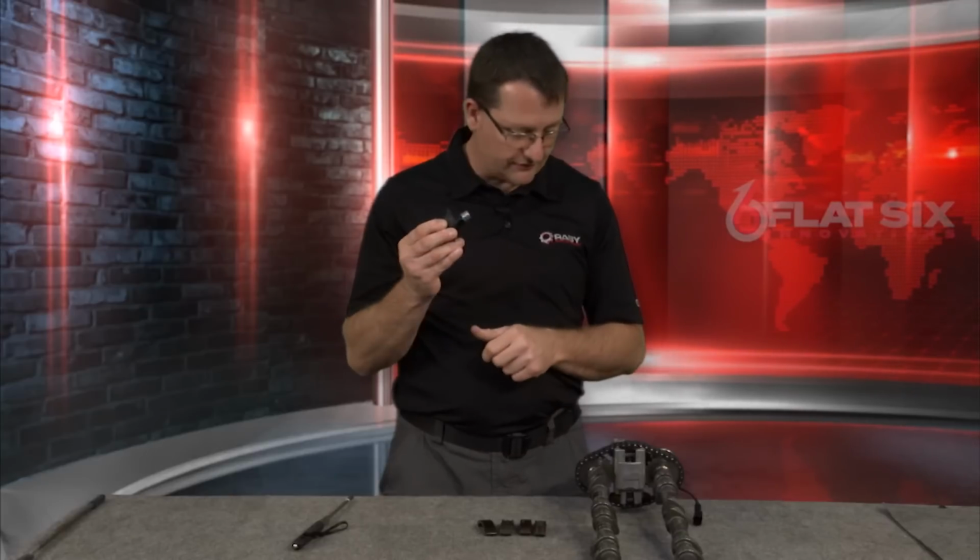So we've talked a bit about the camshaft deviation, what it is. Basically, it's the difference between the crankshaft position and the camshaft positions on bank 1 or bank 2 measured in degrees, okay? We talked about what recognizes that being the camshaft position sensor, what it looks to on the camshaft, and now we're going to talk about the 5-chain specifically and what plays into those big camshaft deviations.